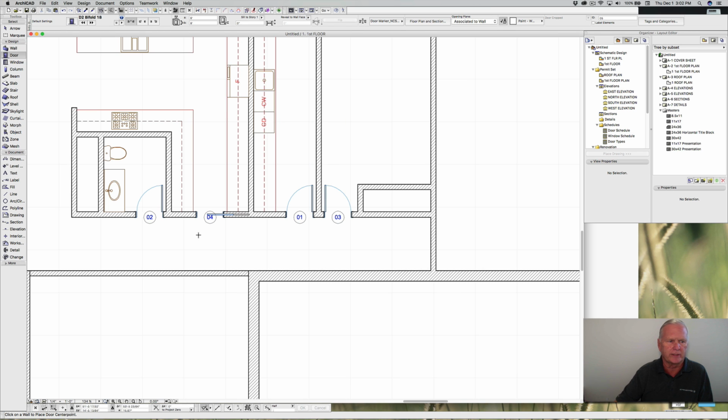We'll say OK. We come over here, we find a tick mark. That puts us in the center of that closet. Click on the side we want to go to. Slide over here to this closet. We're going to put doors on this side. We get our tick mark, special snap point as Graphisoft calls it. Click, and we've got our bifold doors in there.